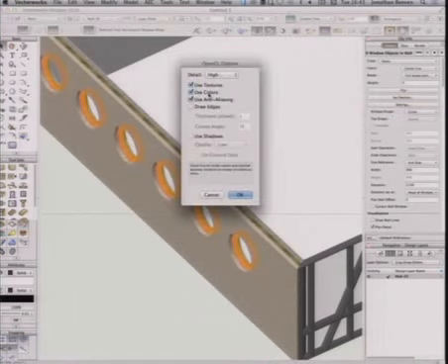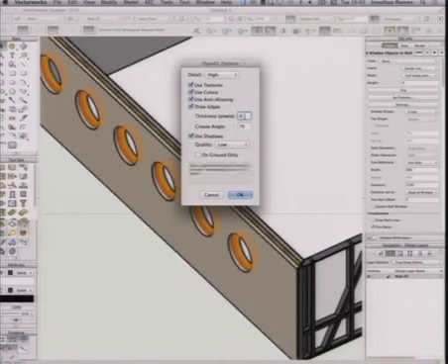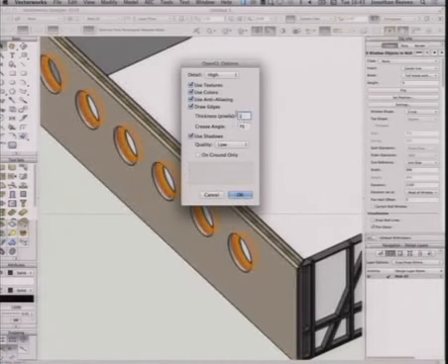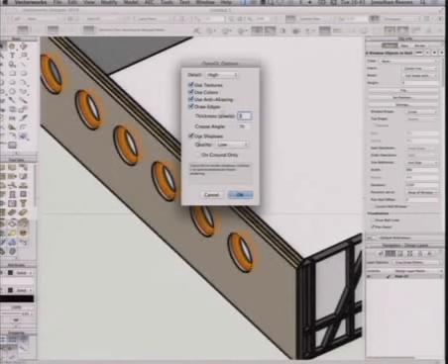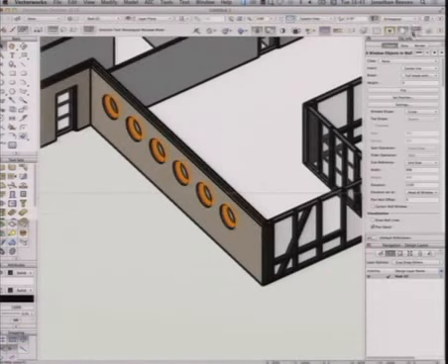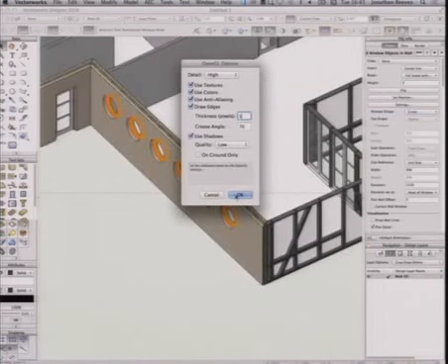Another thing that I love about Renderworks is just a simple one, edges and shadows. And you've got now a really nice feature. BitBlap didn't mention this. It was a lovely feature. You can beef up the line weight. How does that look on screen? Can you see that okay? So you can present it in quite a marker pen style to your client, quite fudgy. Or we can make it a little bit more refined. Let's go for 1. And there we go.